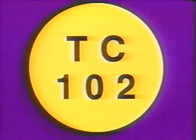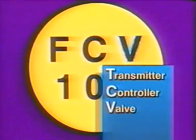If a controller is a blind controller, there is usually no middle letter in the symbol. For example, this symbol indicates a temperature controller that doesn't record or indicate. These are some of the letters used to indicate the names of instruments. The letter V is used to indicate a valve.